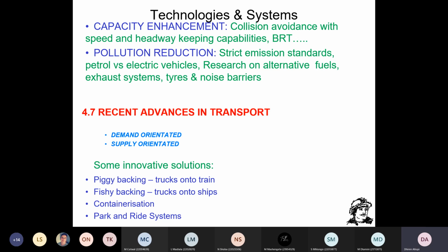So you then traveling in your motor car and you're stuck in traffic on the remaining 1, 2, or 3 lanes. And you then decide it's much easier for you to get onto the BRT system. You will get to work much more quickly because it has its own separate right of way, free of congestion, able to maintain speeds. Sometimes they're even given priority at intersections, depending on the design of the BRT system. So, and yes, as long as you can avoid collisions, then you can increase capacity. We did speak about intersections, for example, that are capacity inhibitors.